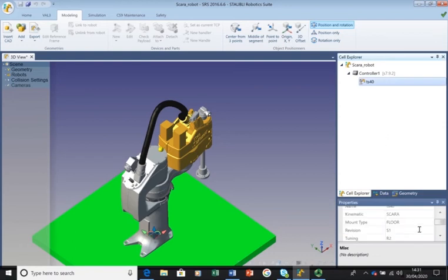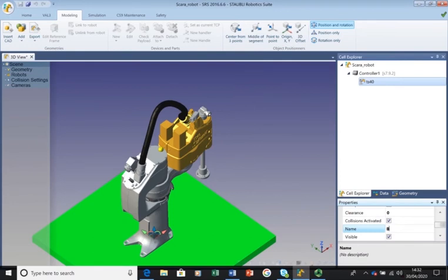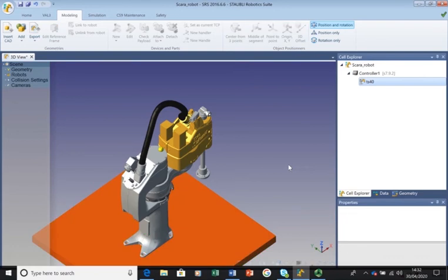But actually, let's just have a look through. Okay, I just wanted to change the name of it as well. Box is not a great name, so let's call it bench. Now what we need to do is move it because it's slightly too high. It was 50 millimeters thick, and the way it does it is 25 up and 25 down from the 0 where the bench is. So we need to just push it down by 25.